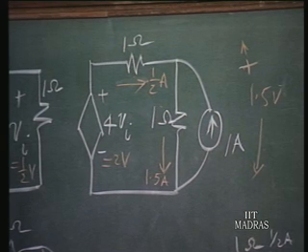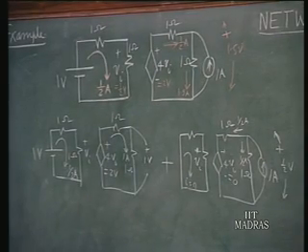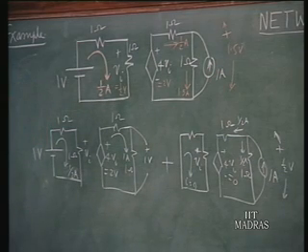So now this particular example illustrates the application of the superposition theorem when dependent sources are also present. As I pointed out, the dependent sources must be kept intact when you are considering the application of each independent source at a time.